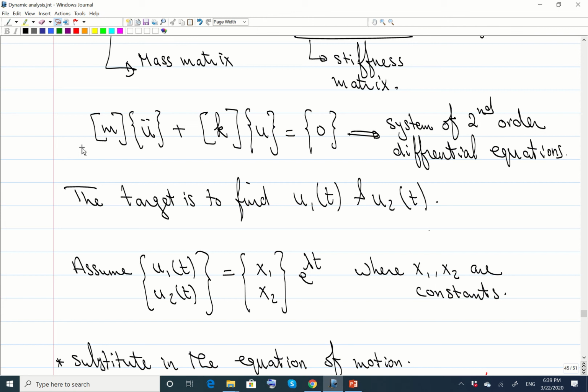If you have just a single-story building, you only have one natural frequency, as we did with the single degree of freedom when you had only a one-story building, okay? So when we have a 40-story building, we have 40 natural periods. Only the lowest mode of vibration, the smallest frequency, will contribute the highest value to the amplitude of motion.